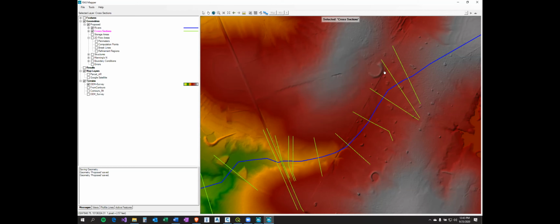And then you take your combined surface and export that as a DEM so that you can bring it into RAS. No, sir. You export your survey, your field survey, at whatever resolution you want to live with. I've done 1 foot before. You can do 2 foot or 3 foot DEM resolution. You'll export your survey as a DEM, as its own separate DEM surface. Then you'll go into HEC-RAS and you'll let HEC-RAS do the compositing with the downloaded GIS data. Just like you do in Civil 3D, HEC-RAS will allow you to paste surfaces in the order that you want them to be pasted.